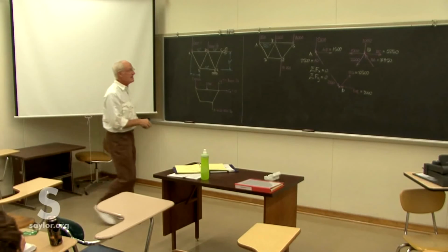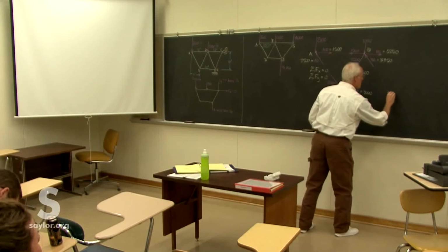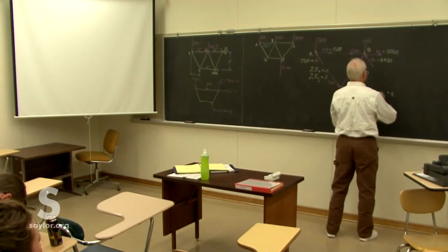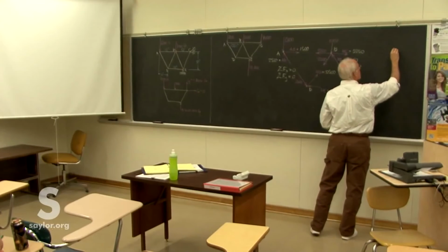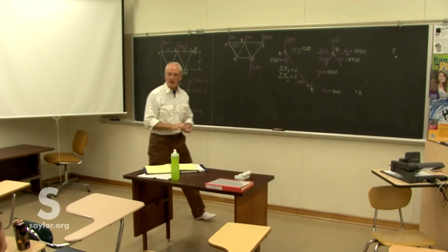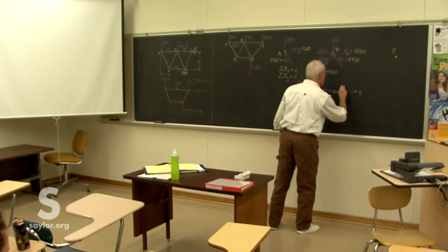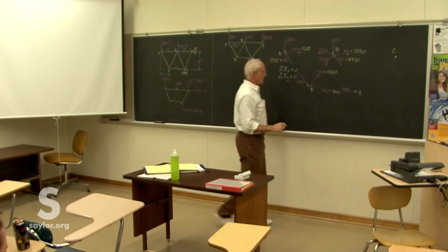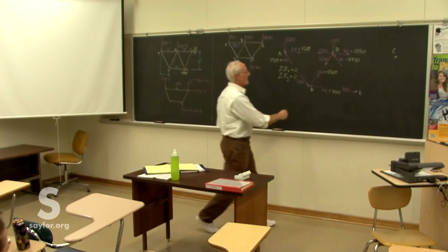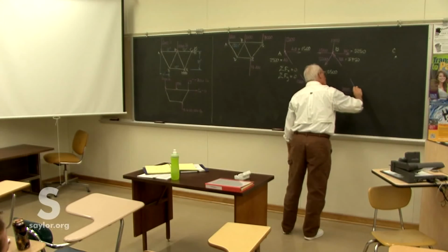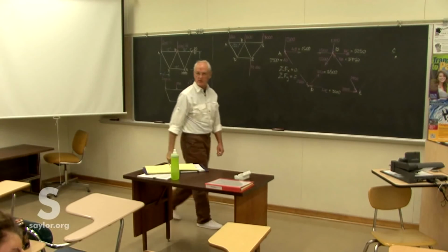All right, we keep going until we finish the problem. We've got two more joints to do, E and C. If you know any forces, you put them in. Let's see. We know that's got to be that way, and is 3 grand, because that was what was going on at the other end of it. We know that one's 3,750, simply because that's what was going on at the other end of it.